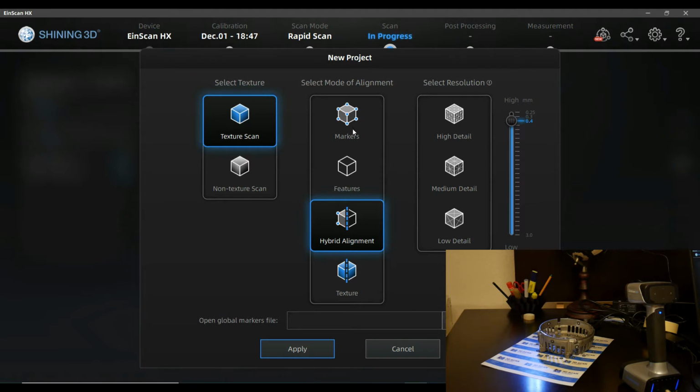Imagine you have, for example, an egg, and if you break it into pieces, of course in the scanner all of these pieces have to have overlapping. They are stitched together, and stitched together each of these shells that you are shooting as a 3D picture, let's name it like this, gives you in the end a volume, body or a complex surface that you can use for your technical purpose.